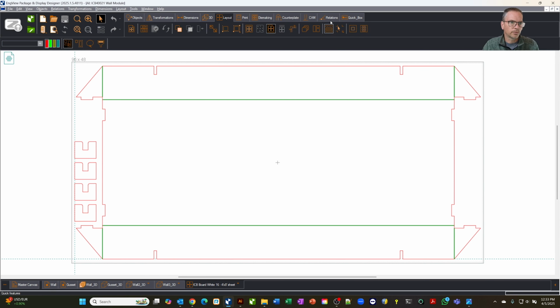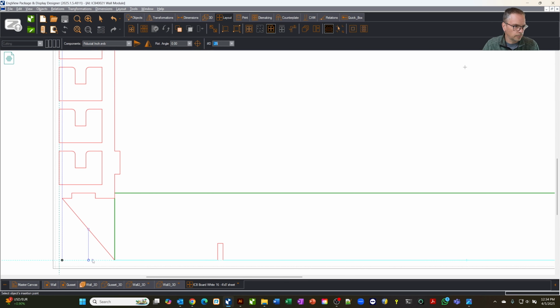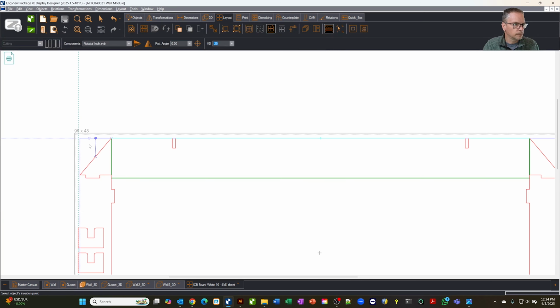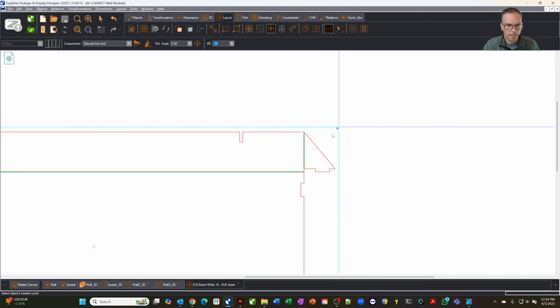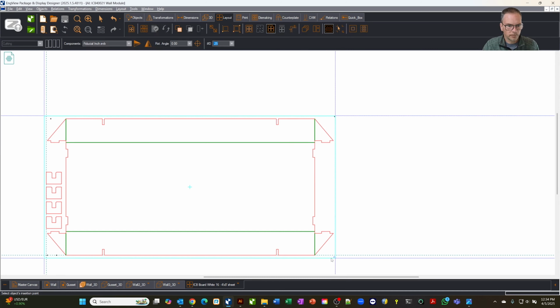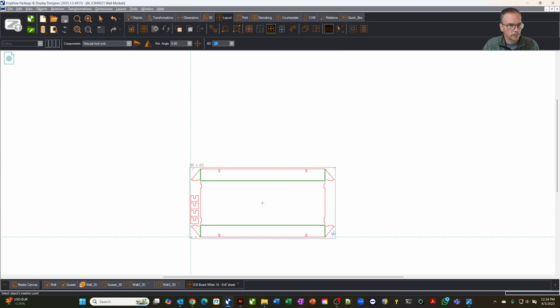So we'll go to this little tool right under, you can see right from the end, it looks like a little hamburger. And we'll grab our fiducials. We can put in a diameter of our fiducials here and then start to drag them out. So let's just put a couple in, maybe right here. Maybe we'll put another one there, another one here, probably far in the corner there, and maybe right there. Okay. And you get the idea.